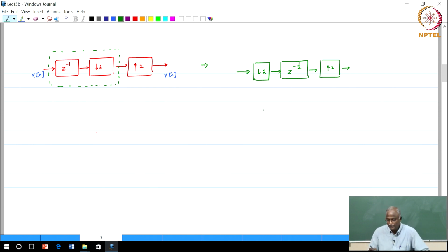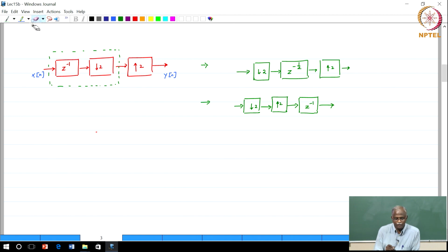You can shift the delays even further, which then says you must take the polynomial and raise it to the power L. So we come up with downsample by a factor of 2, upsample by a factor of 2, and z inverse. The argument is that I applied the noble identities, and I have obtained an equal expression. Whether it is simpler or better does not matter. Is this correct? Applying the noble identities looks like it's okay. What he has done seems okay.